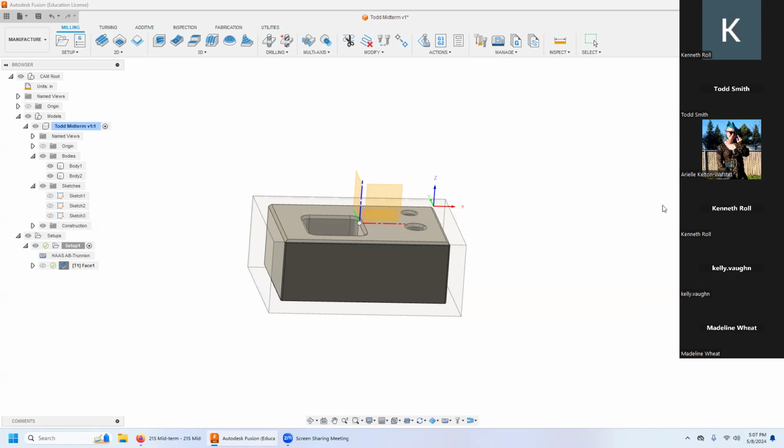And linking. Keep tool down. I want this to be something ridiculous. Extend before retract, so it leaves the stock first. No vertical lead in.